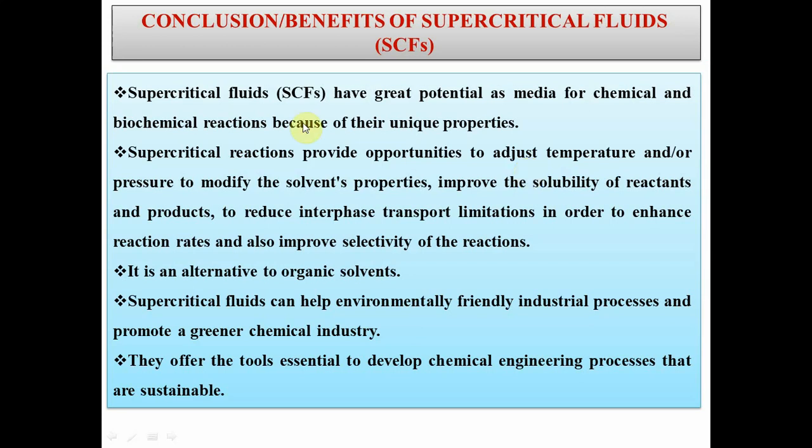Conclusions. Supercritical fluids have great potential as media for chemical and biochemical reactions because of their unique properties. Supercritical reactions provide the opportunity to adjust temperature or pressure to modify solvent properties, improve the solubility of reactants and products, and reduce interface transport limitation in order to enhance reaction rate and also improve selectivity of the reaction. It is an alternative to organic solvents.